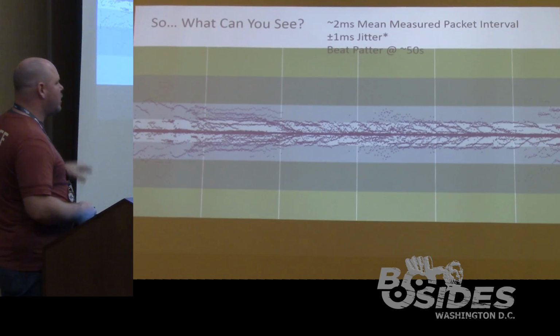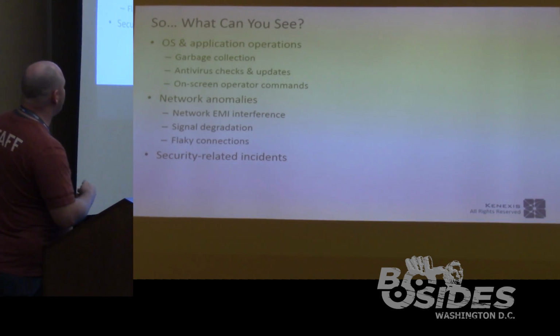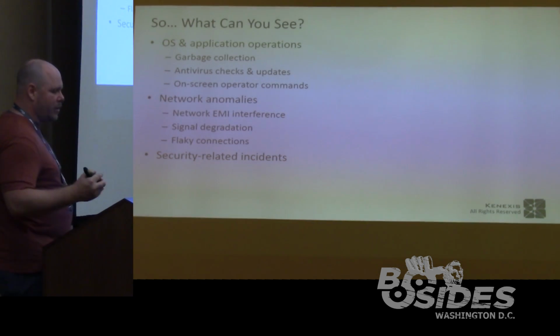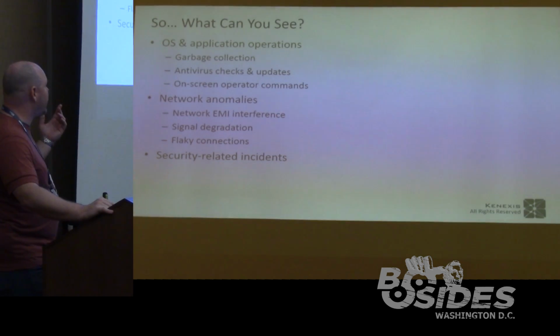So a lot of these are more individual testing. I said, so what's causing some of these? It may be garbage collection. Antivirus checks and updates are terrible. Human-machine interfaces, HMIs, will lock up when antivirus kicks in. Some AV vendors are worse than others at it too.